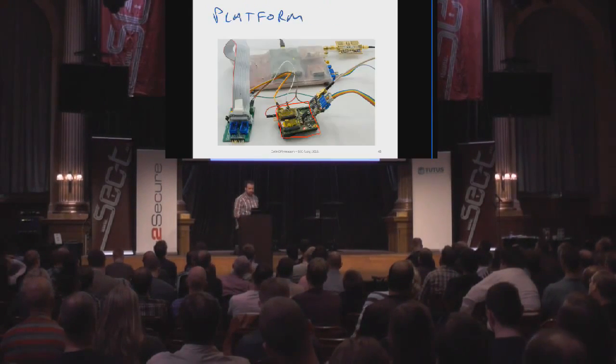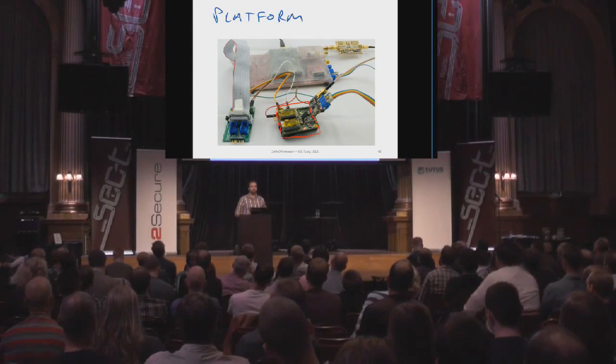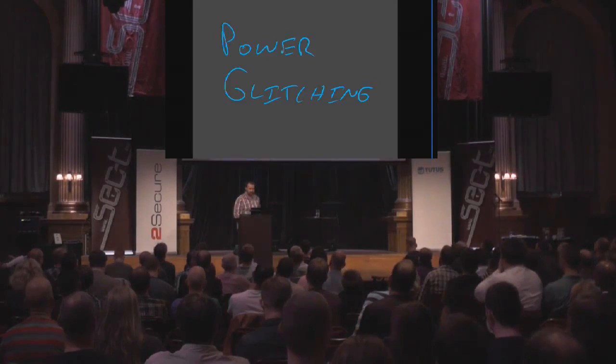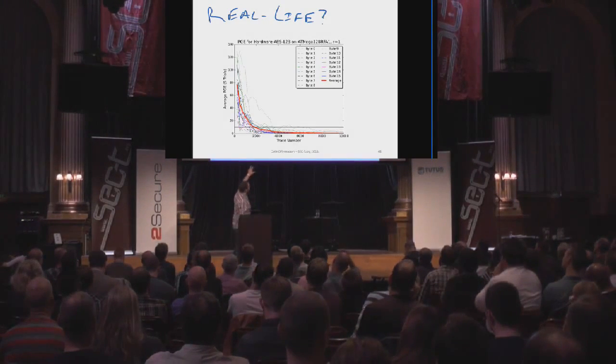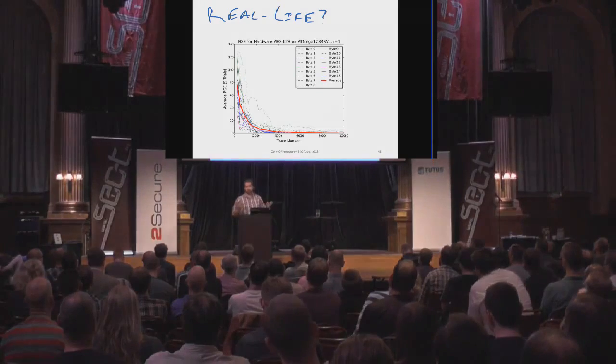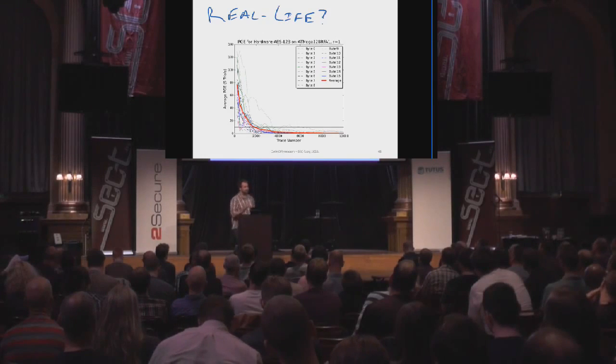The hardware itself, so this node internally has a hardware AES accelerator, so it's not doing the software version I was just showing you. It actually has a peripheral in the micro that's decrypting it. As it turns out, this hardware AES engine is vulnerable to the side channel power analysis attack, which is mostly the case for any device that's not designed to be resistant to it. So your credit card is designed to be resistant. An off-the-shelf microcontroller is not.